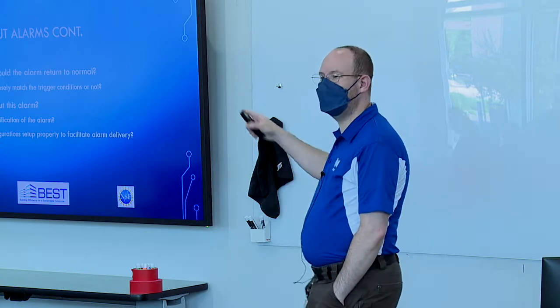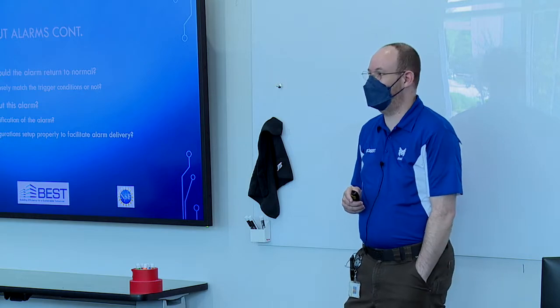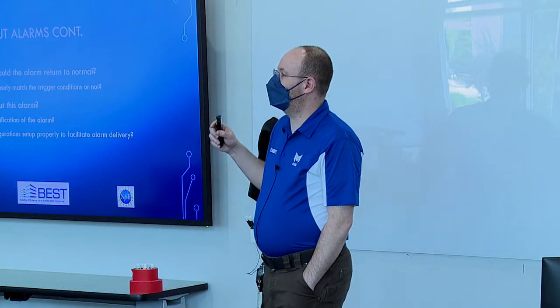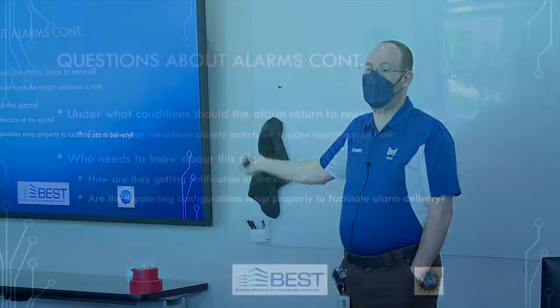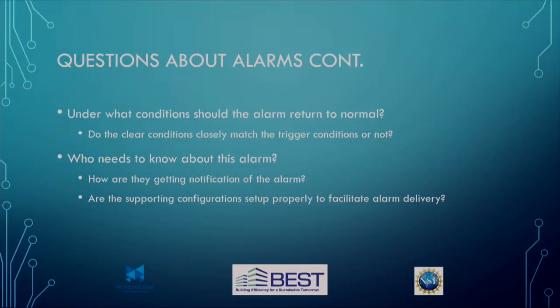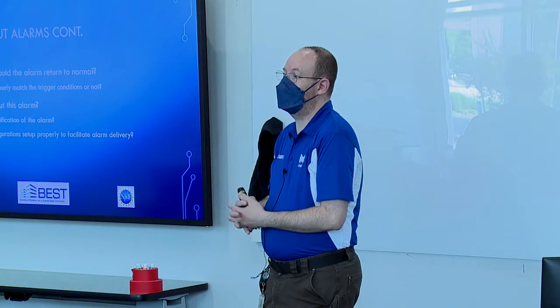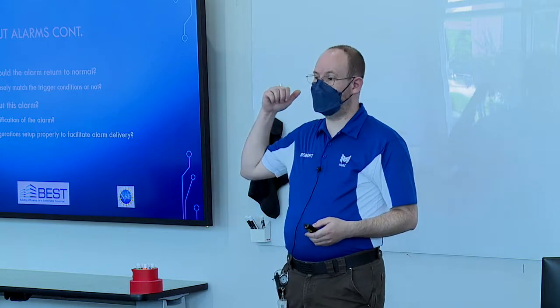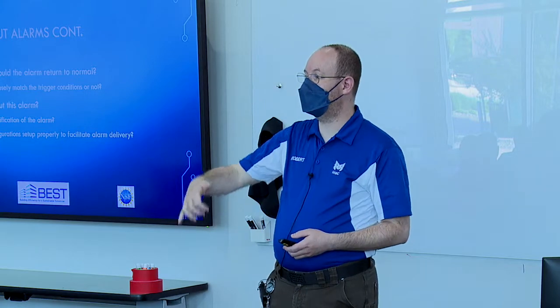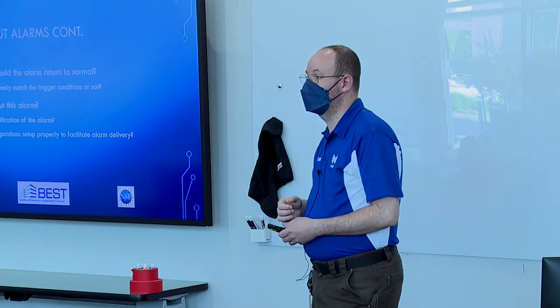Anyway, back to alarms before I get off topic in a bad area. We have to figure out when alarms are going to go back to normal. We also need to figure out who needs to know about alarms. How are the notifications getting sent? Do we have the infrastructure in place to make sure those alarms get where they need to? Are we constantly texting the manager's phone and making him or her dispatch those alarms?